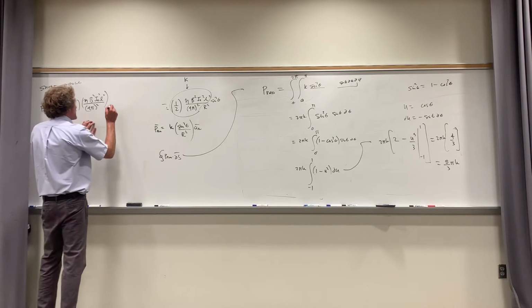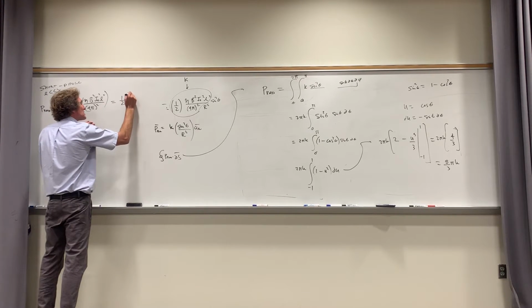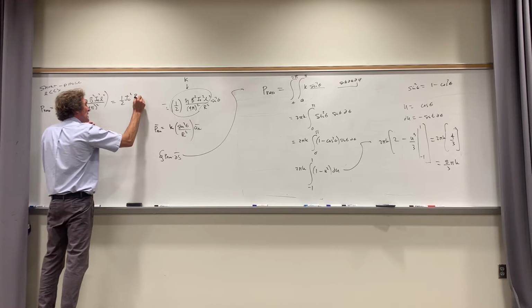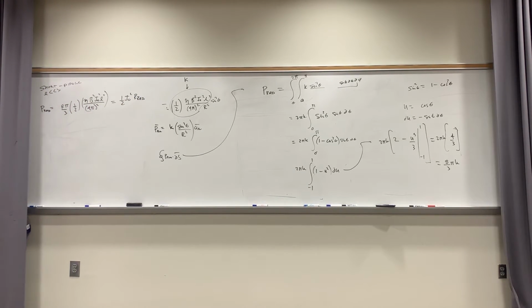So this power radiated is really equated to 1/2 I naught squared times R rad. Here, that's the radiation resistance. It's the effective resistance of the wire, due to the actual power transformation from acceleration of charge to photons, if that makes sense. Because remember, electrical current moving is not photons, but if it's accelerating, it launches photons.